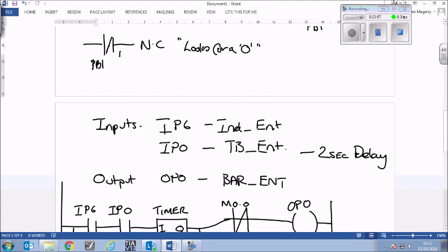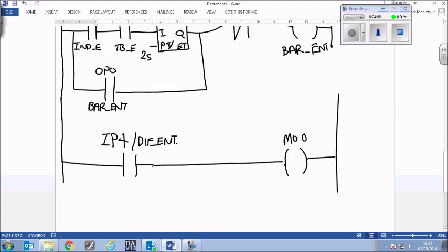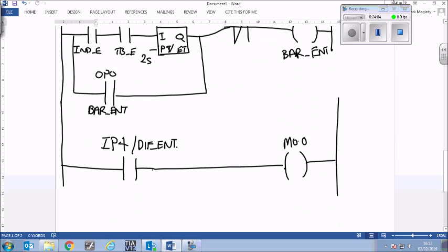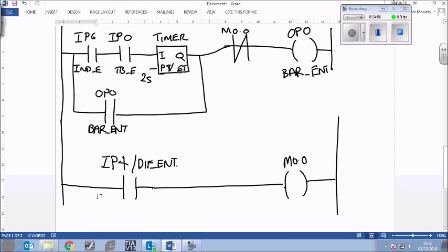So, thinking back to this part here, this IP4, so that's the sensor. So you're at stage 1, the car is just on top of the inductive sensor and the ticket button's being pressed. So currently, is IP4 active or inactive? So it looks for a 1, does it find a 1?